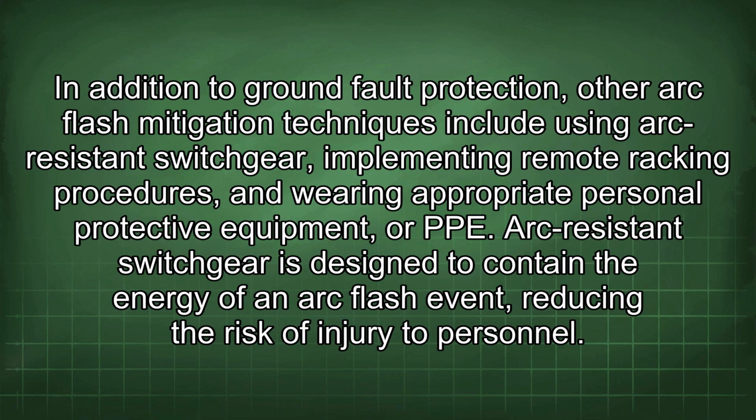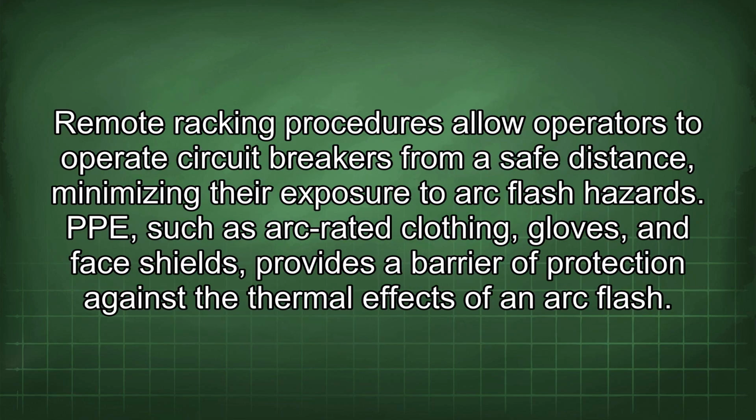Arc-resistant switchgear is designed to contain the energy of an arc flash event, reducing the risk of injury to personnel. Remote racking procedures allow operators to operate circuit breakers from a safe distance, minimizing their exposure to arc flash hazards. PPE, such as arc-rated clothing, gloves, and face shields, provides a barrier of protection against the thermal effects of an arc flash.